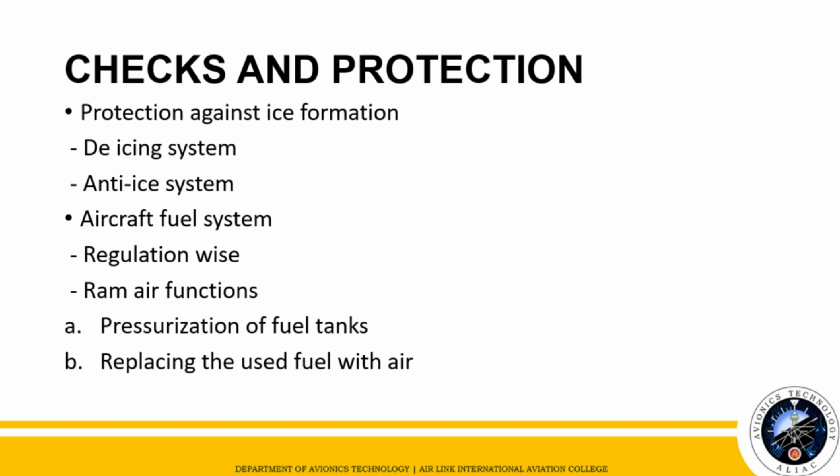Each tank will potentially be equipped with internal fuel pumps, and have the associated valves and plumbing to feed the engine, allow refueling, isolate the individual tanks, and in some applications allow for fuel dumping or for optimization of aircraft center of gravity.